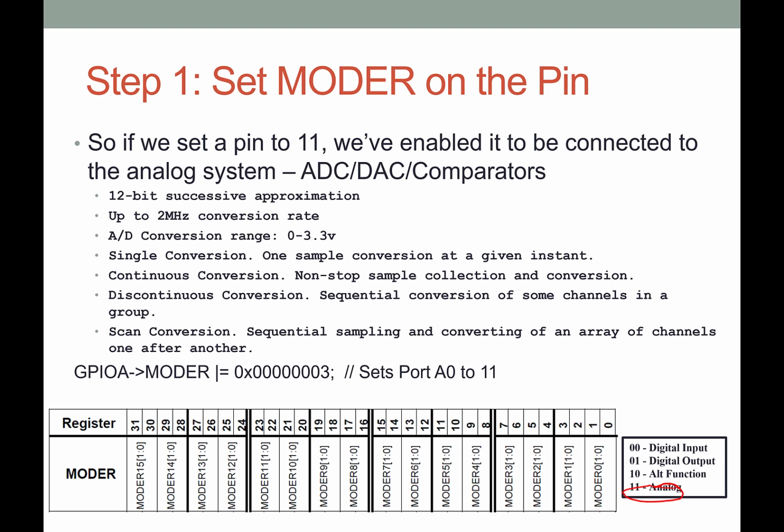So notice that the 10-bit we just talked about was 1024. 12-bit is going to be 2 squared, or 4 times higher than that. So that's going to be 4 times 1024, or 4096. So our standard that you're going to see in your template file is something that will give you the idea that you have 4096 levels in there. So be aware of that.